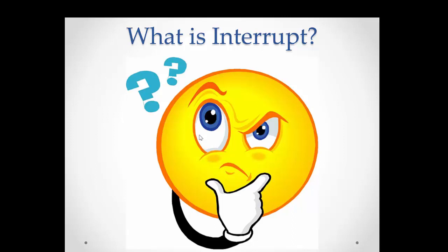So now we have the software interrupt, such as the internal interrupt, and we have hardware interrupt, such as the interrupt on change, which are associated with keyboards. We also have the interrupt which is basically called the external interrupt. That's what we are going to discuss today.